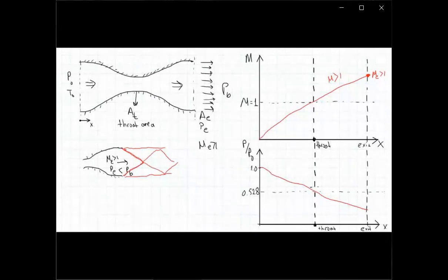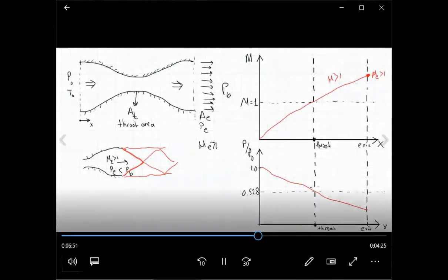Simply because our jet exit pressure is expanded more than what it should be expanded to. Because of the overexpansion, the static pressure dropped more. So in order to reach the higher pressure in the outside world, it can only reach these higher pressure levels through the existence of shock waves.